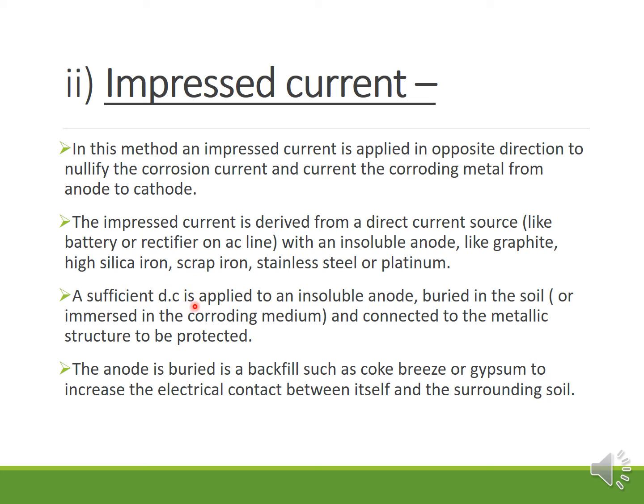Sufficient DC is applied to an insoluble anode buried under the soil and connected to the metallic structure to be protected. The anode is buried in a backfill such as coke breeze or gypsum to increase electrical contact between itself and the surroundings.